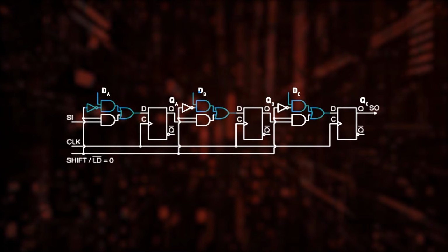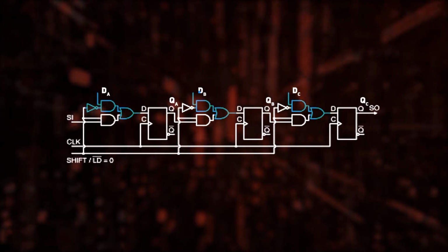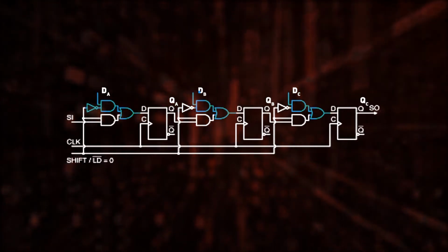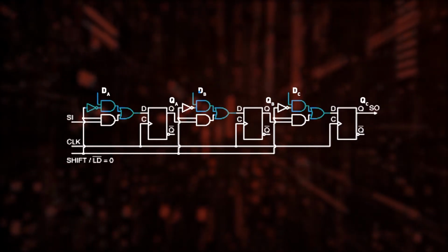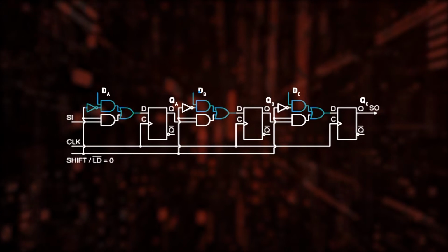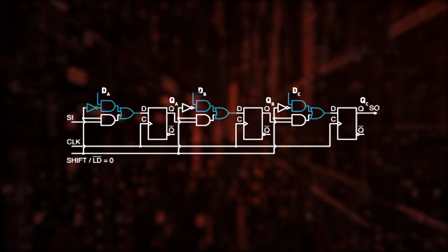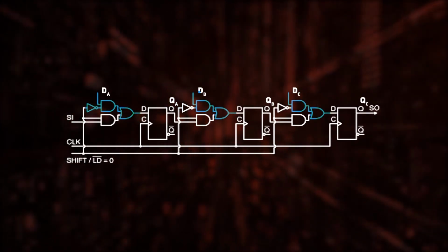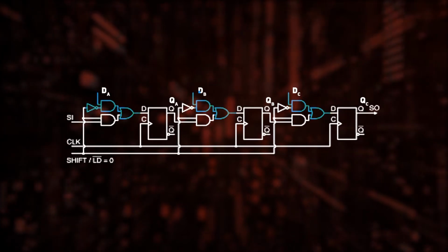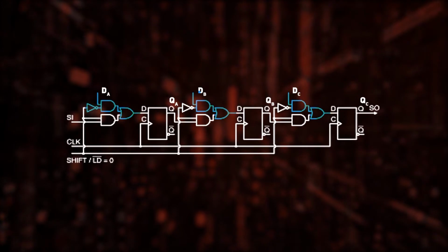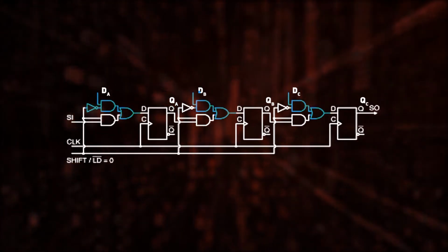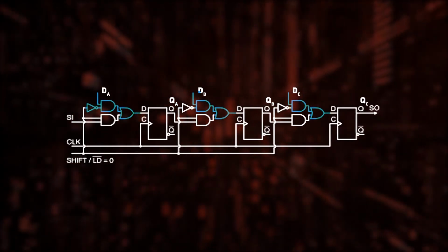How should we fix this issue? The solution is we should design the circuit in such a way that it will receive one input at a time, whether it is external or internal. The additional gates that you see above the flip-flops in the diagram are used for that. They are nothing but the combinational gates which control the loading or the flow of the data.